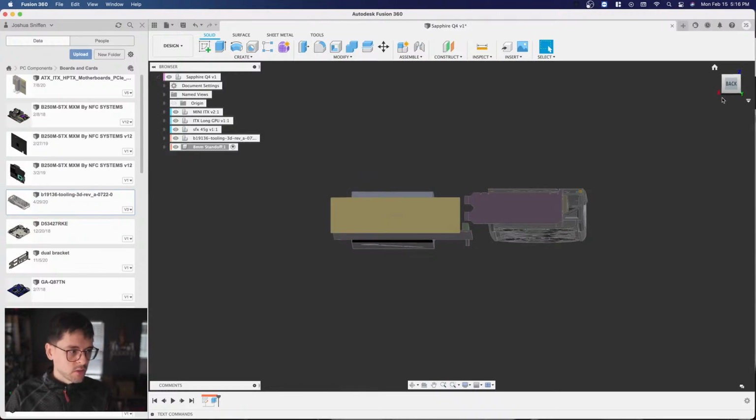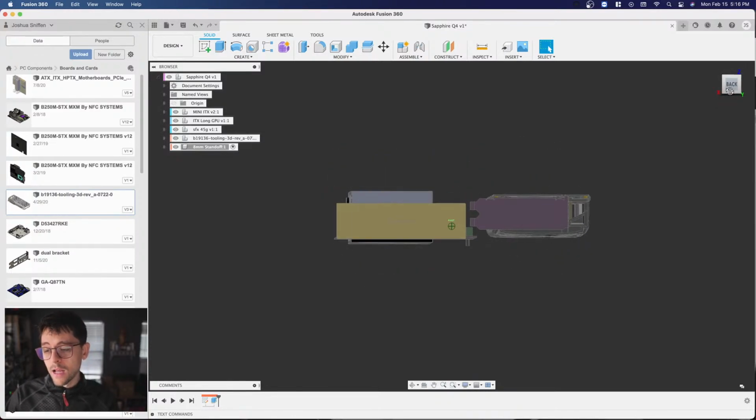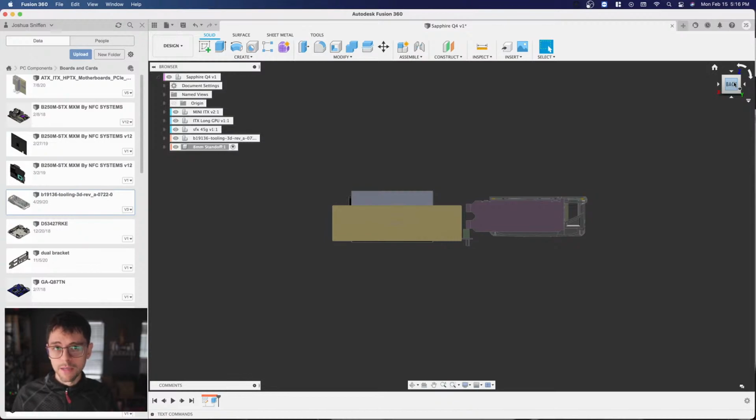MackeyWack says, some more considerations for the manufacturing process. Tooling limitation. Yeah, that's a very big deal, and that becomes a major problem as we move forward in the design. To start off with, I'm just thinking ahead about what things I know I need to do when arranging the hardware. The actual specific tooling stuff we can work out as we're making the individual parts. But I know that I want this to be able to be made by simple bending processes by you guys ordering it from a company like SendCutSend. So I know that I need a good amount of space for the I/O shield to be raised up from that bottom bend. So I know that that's going to be 8 millimeters.